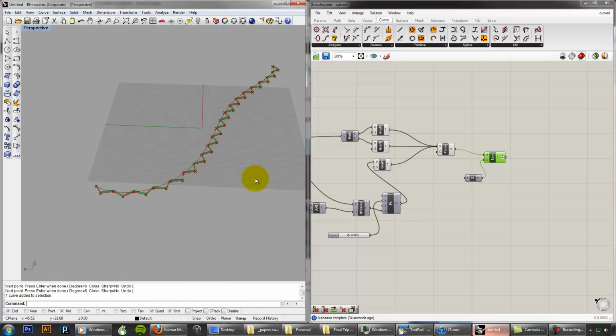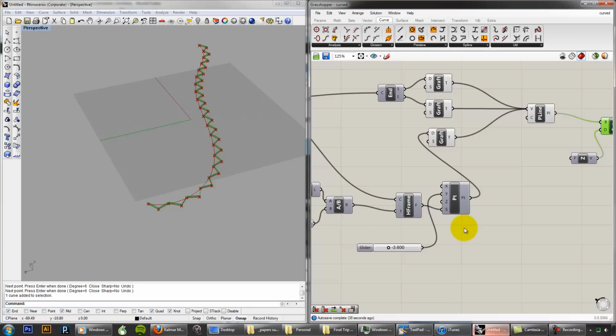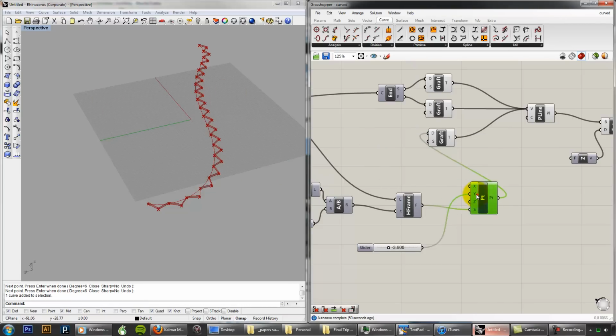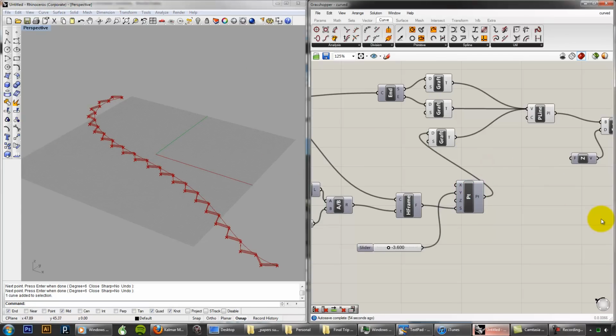If you're going to do something like a canopy, if you're going to change the orientation of it, what you want to make sure to pay attention to would be the coordinate plane for the point. You may need a perpendicular frame depending upon how you're modeling it. But the idea is that you need a local coordinate in order to get that offset. And that's it. I'll see you in the next part.